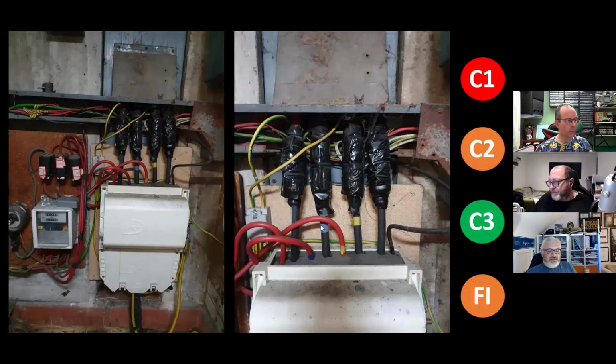What's everyone coding that as then? Because we've gone C2 50%. What's the rest? FIs, FI is 30%. I'm with FIs on identifying the earthing system. C3s are 10%, 10% C1s. So I'm going to go with either C2 or FI. That's the beauty of some of these codes. It does require improving without a doubt. But we need to analyze: yes, it requires improvement to what regulations, or is there a potential danger there? Or do we just need to investigate further first?